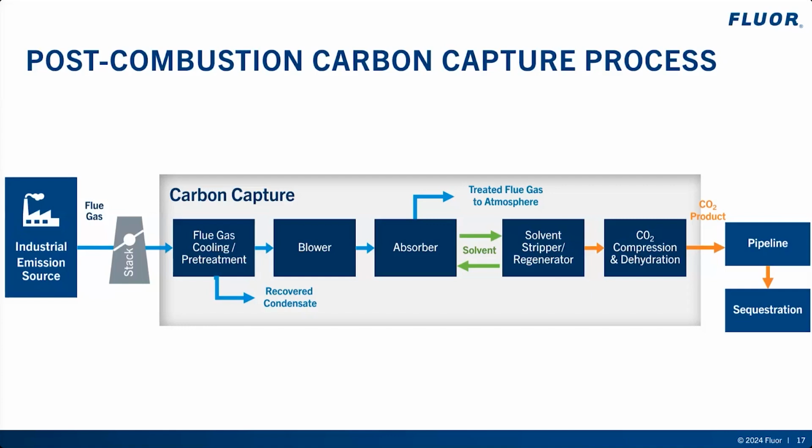The temperature required for CO2 stripping from the solvent results in water boiling in the bottom of the regenerator and produces steam. The steam further acts as a stripping agent of the CO2 from the solvent. At the top of the regenerator, the overhead must be cooled to condense and recover the associated steam generated in the system.